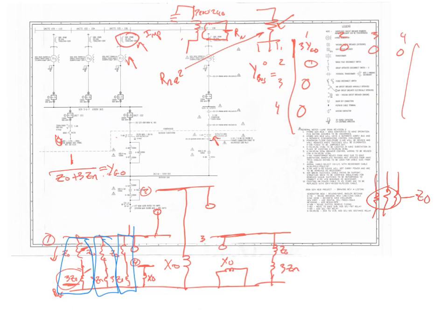Ralph, could you go over again really quick why the delta for the negative sequence goes to reference? Negative sequence doesn't go to reference. Oh no, this is the zero sequence that we're looking at. Right. Positive and negative sequence don't go to ground, they just pass right on through. Then the only thing that changes with the negative sequence is that you take out the generators for the positive sequence. Correct.